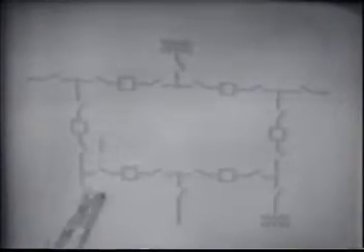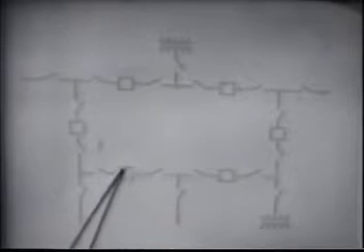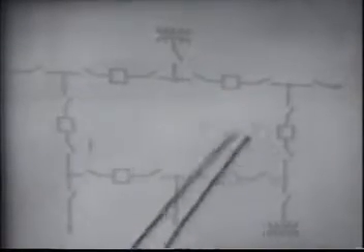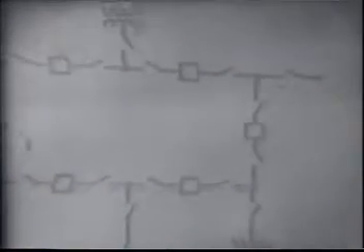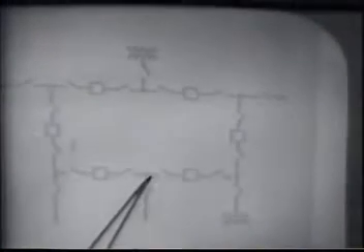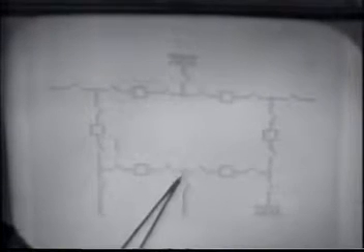It's a loop of different bus sections to which circuits are connected, and between the bus sections we have a circuit breaker or a transformer. That is between each element of the bus, a line or a transformer, we have a circuit breaker.